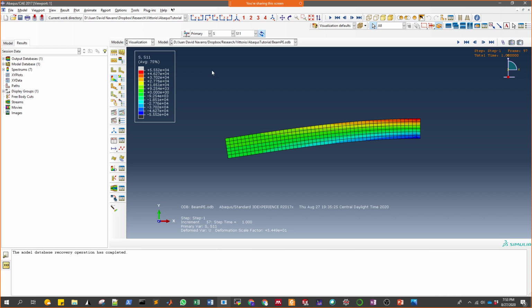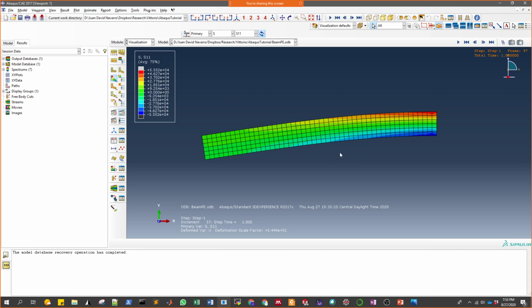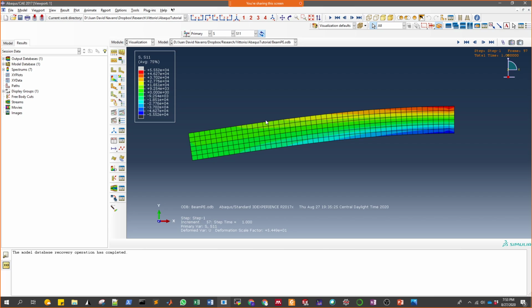So this one is a square cross section, right? No, well, yes, sorry. And that's because the height that I used was 1 and the thickness was also 1. So can you also see what's happening on the cross sections? In this case, no, because I'm using plain elements. To do so, I will need 3D elements.